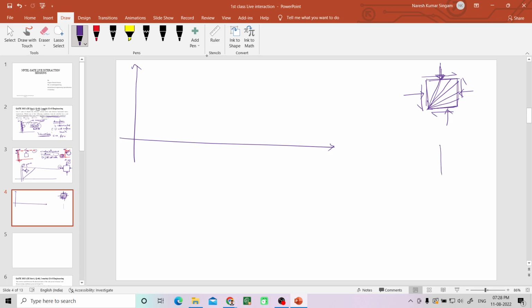So I am focusing only on one plane, let us say. Because of the load which is applied on the soil element, finally it fails. Before failure or after failure or during the failure or at any point of applying the load, what happens? Every plane is subjected to some normal stress and some shear stress, because of the loads which you applied on the element. Every plane is subjected to some combination of sigma and tau. Now if you take sigma on the x axis and tau on the y axis, at any point of loading, let us say at t equal to t1, this is the condition of the soil element. So every plane has a different combination of sigma and tau.